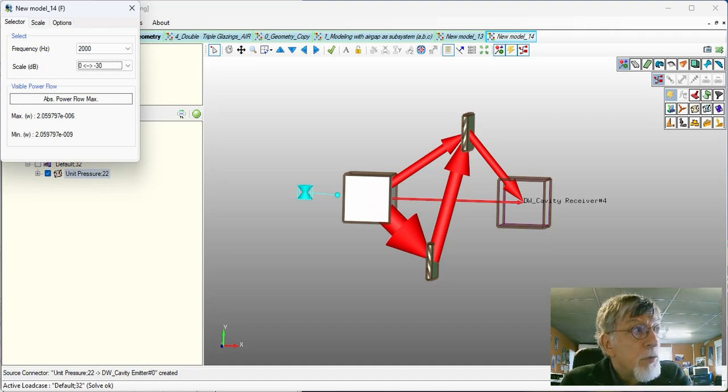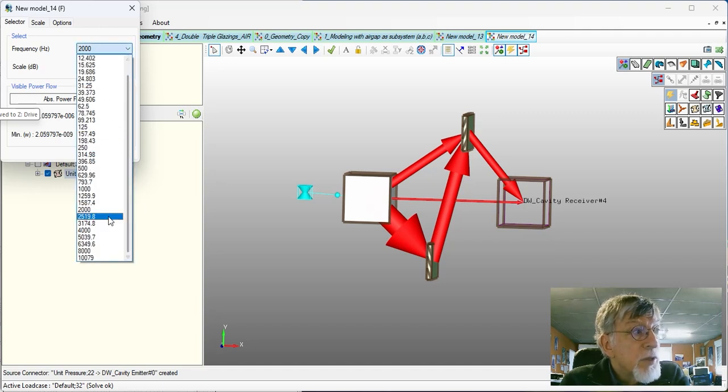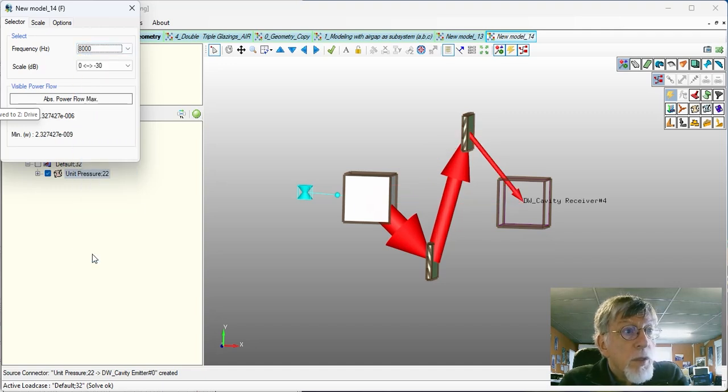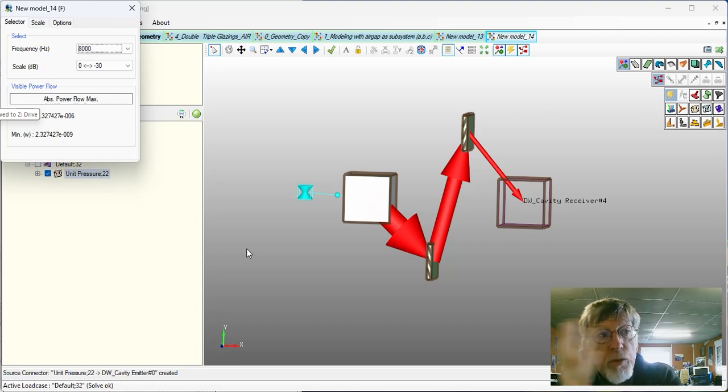And if I go to 10 kHz, it's still the case, in fact, all other paths are eliminated. And then you see the main path quickly. So you have, in this problem, two main paths: the direct non-resonant path for the two cavities, and the mechanical path at high frequency that has to be scaled against the mechanical coupling loss factor between the two plates.